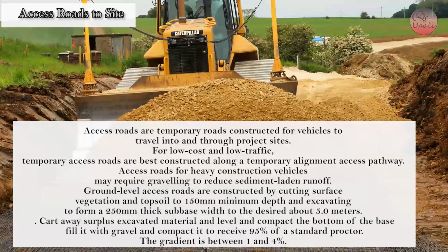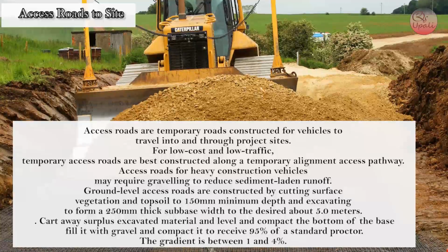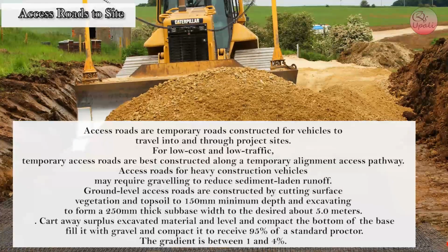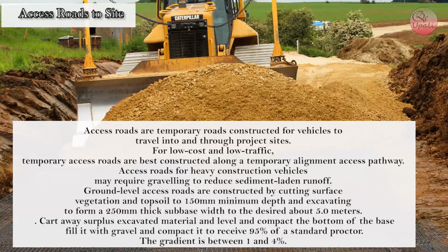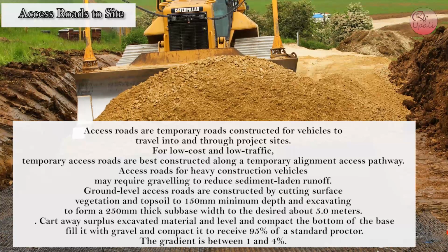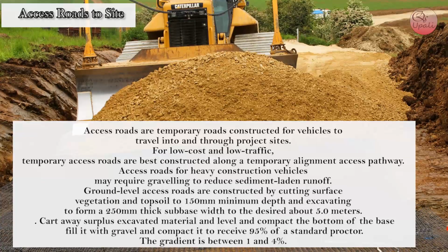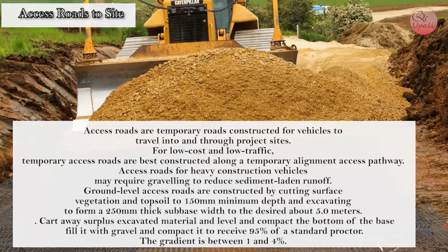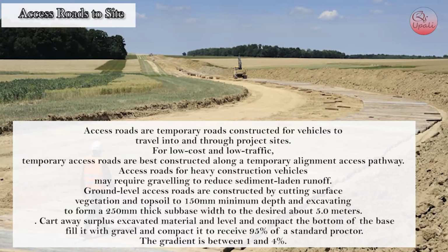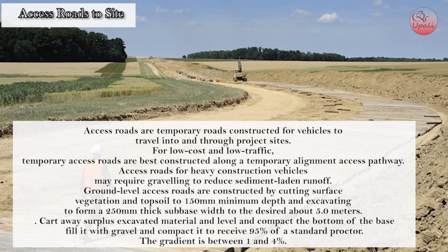Access road to site. Access roads are temporary roads constructed for vehicles to travel into and through project sites. For low-cost and low-traffic, temporary access roads are best constructed along a temporary alignment access pathway. Access roads for heavy construction vehicles may require gravelling to reduce sediment-laden runoff.